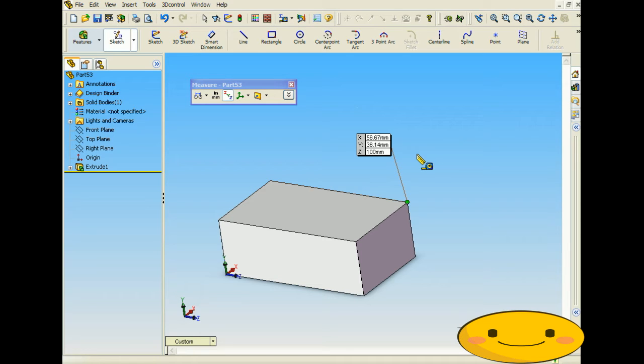So, say I'm working on a door panel or something. When I click on a point on the door panel, it's not going to be a small dimension like that. It's going to be x away from the front left tire or something like that. There's an origin for the whole vehicle, so when you're in the assembly, it's actually position constrained. It's hard to visualize, but every part has a position in the assembly. None of them are really constrained using the assembly constraints, like coincident constraints and whatnot. Usually they just use positioning constraints.